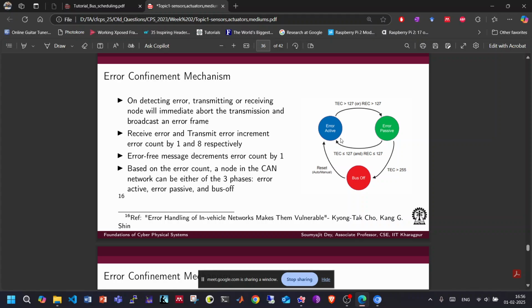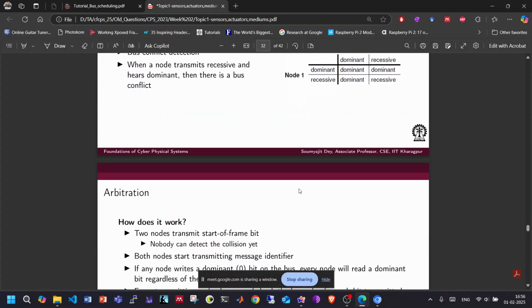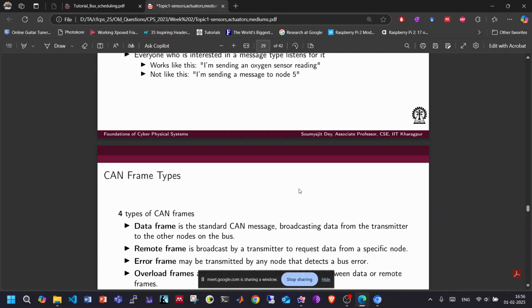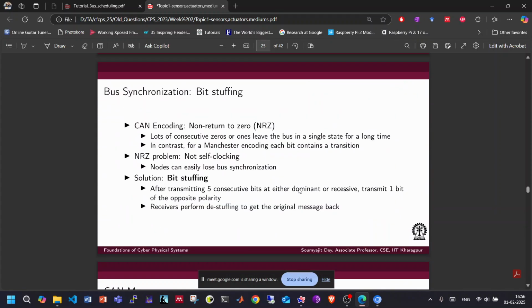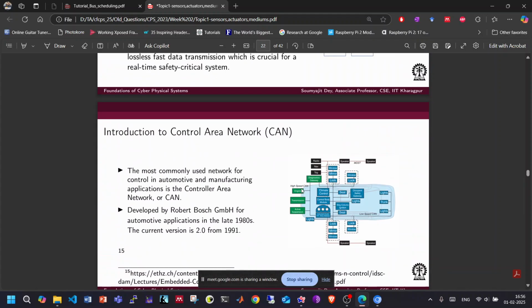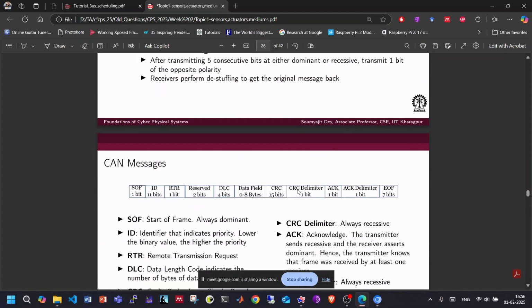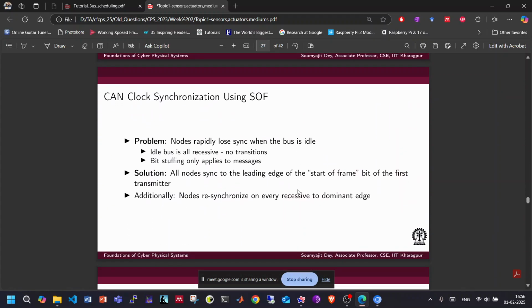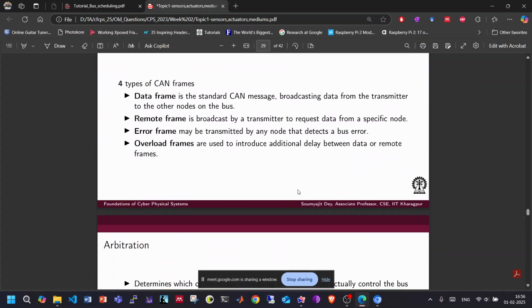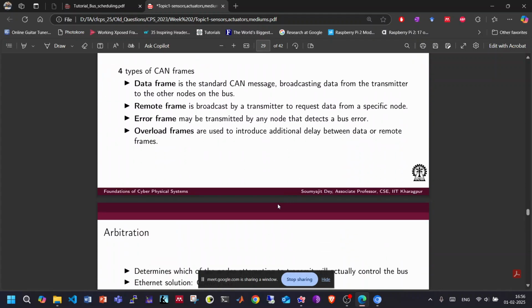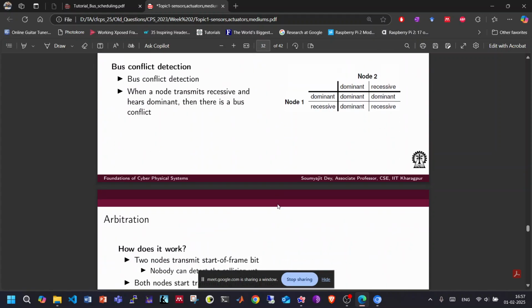Obviously, for that we have to maintain a static mapping, like this ID is transmitted from this certain ECU, like the engine will only transmit IDs 1, 2 and 3, the transmission module will only transmit IDs 3, 4 and 5 or something like that. Static mapping will be there and you will match that, and accordingly you will find out where it came from. The designer decides it like that, and the receivers also verify it on their end. This is how it is done, but the signal is obviously not carrying that data. So that is a drawback of using CAN.